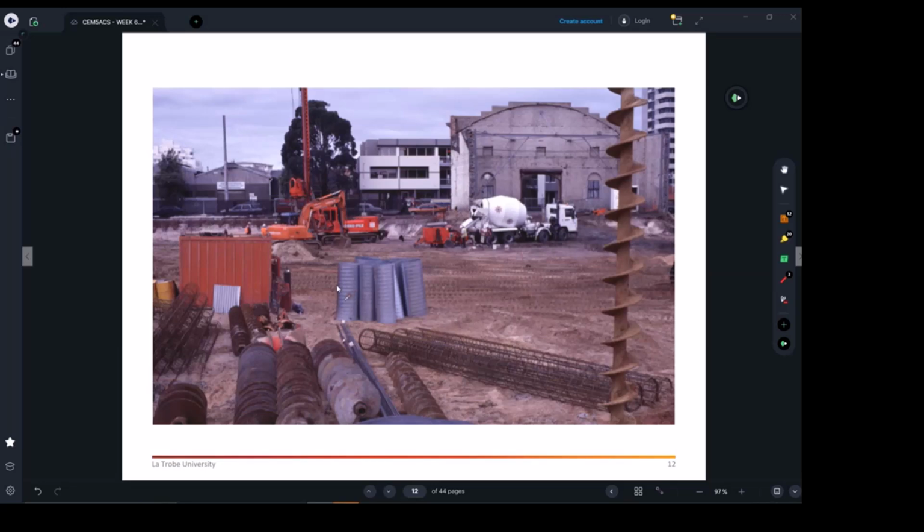They start pouring the concrete and slowly lifting up the auger, making sure the concrete level is above the pouring end for the concrete. After that, they place the steel cages, submerging them into the hole. And as I said before, this is just temporary shoring if required. I usually place it at the first layers, at the top of the hole.